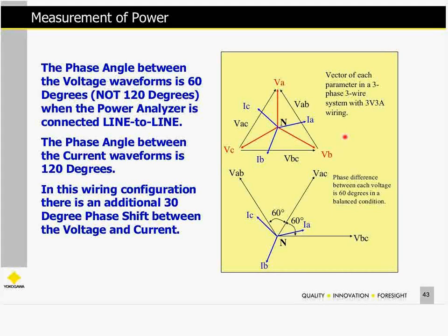So the power analyzer has to take all this into consideration when it's making these measurements. And the main thing is that you're not making a phase measurement. It's not a phase voltage. The voltages are in a delta configuration.